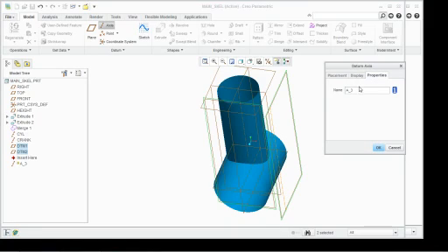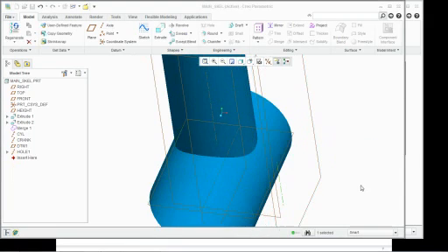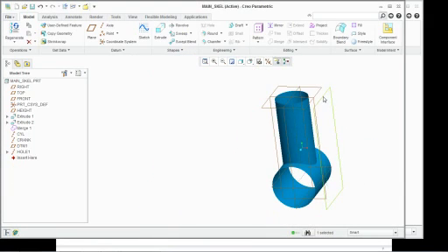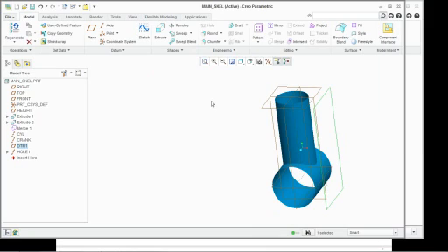And I'm going to take this axis and change the name of it to pole 1, and then take the display and adjust the outline down to a reference of this top face here. Notice that the axis did get shorter. Click OK. Well, maybe I want to take this one here and change that as well, but that's not necessary